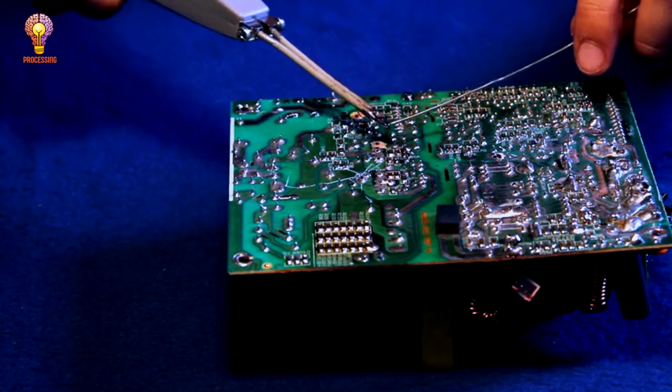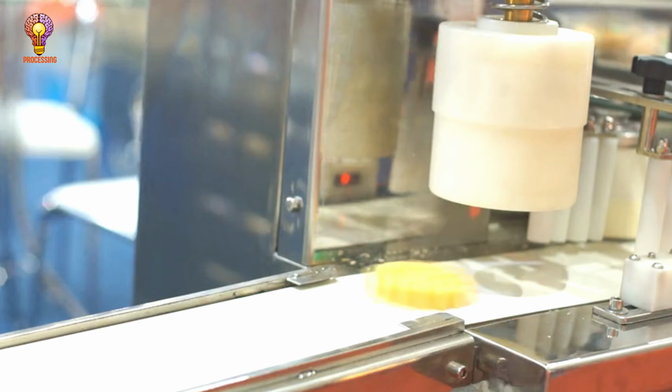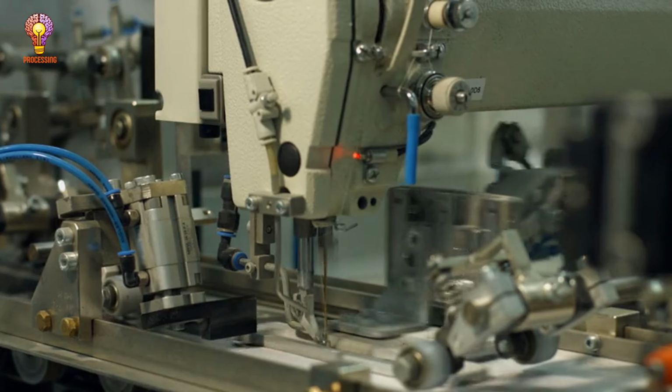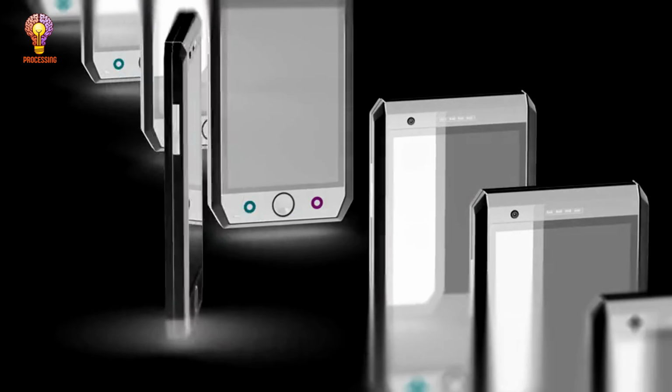Solder paste is applied to secure the components. The PCB is heated in a reflow oven, melting the solder and bonding components. Optical inspection machines check for defects. 4. Phone body and frame production. A. Metal and plastic frame manufacturing.